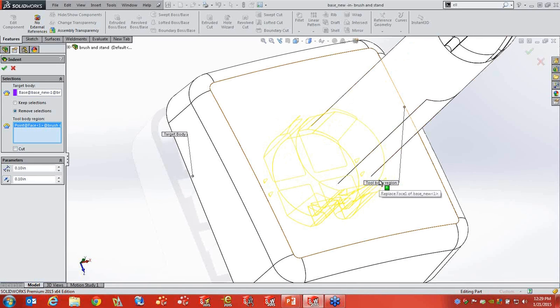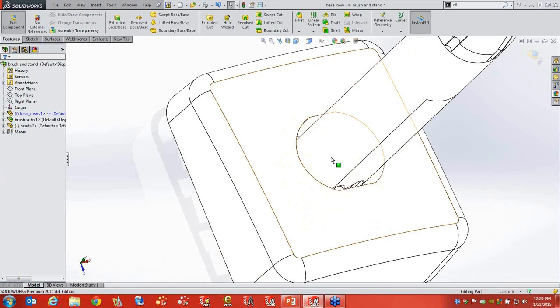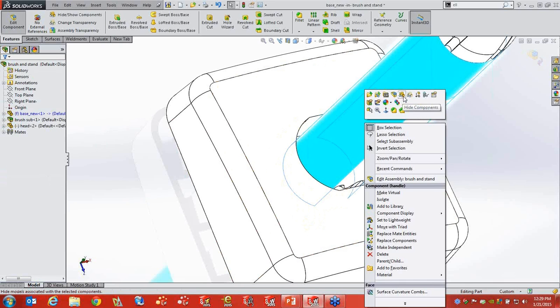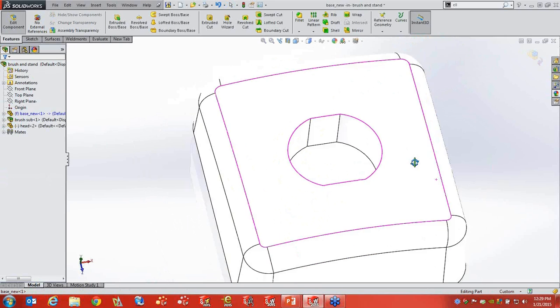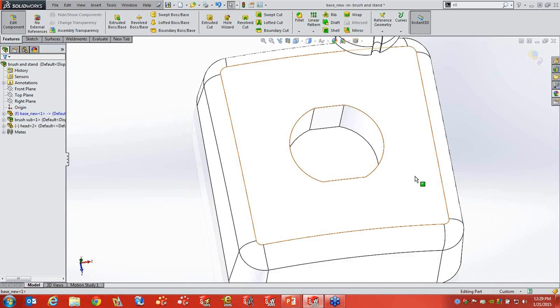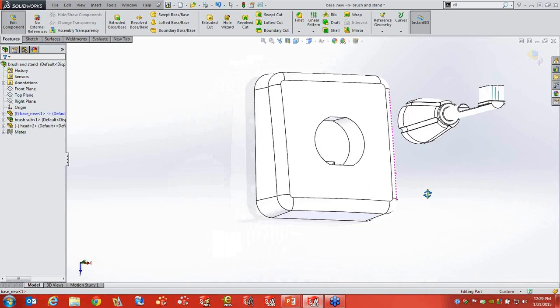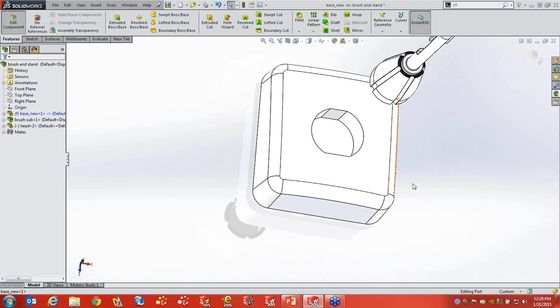It actually just does like a cavity or a Boolean like we're used to in some of the combined commands and cavity commands that we're used to in SolidWorks. But in this case, what we just ended up doing is creating an indentation feature in the other part.